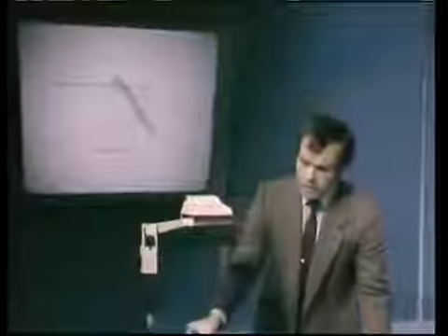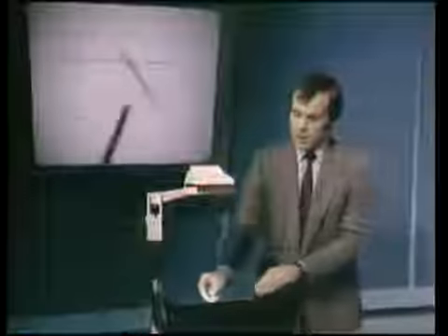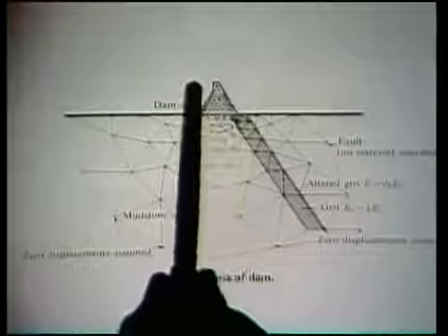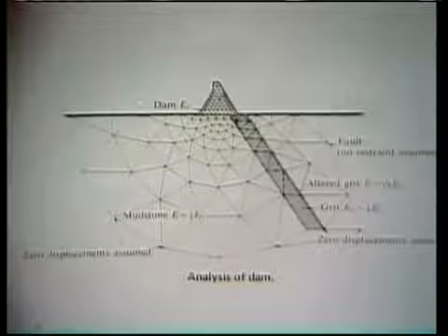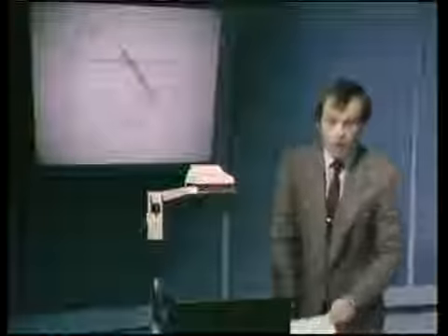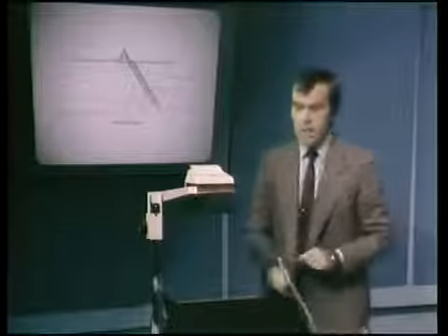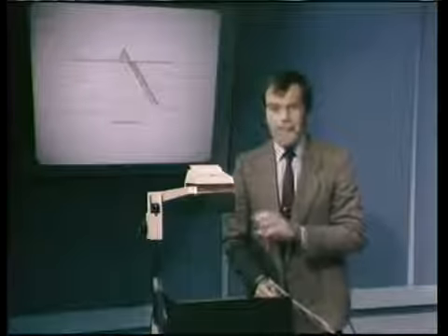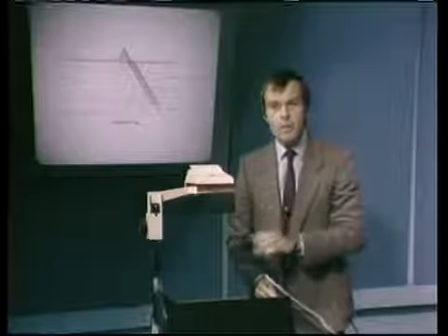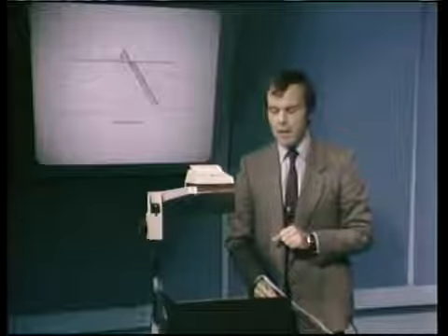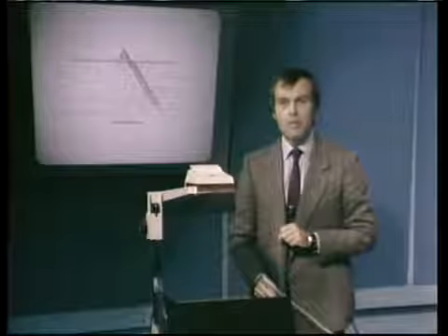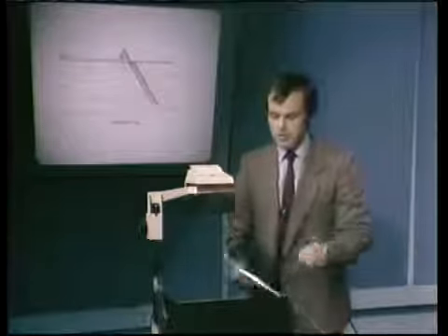Here you see the finite element model of a dam. The earth below the dam was idealized as an assemblage of such elements here, triangular elements now, and the dam itself was also idealized as an assemblage of elements. We will be talking about how such assemblages are best created, what kinds of elements to select, what assumptions are in the selection of these elements, and then how we solve the resulting finite element equilibrium equations.